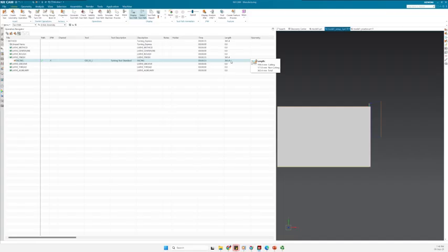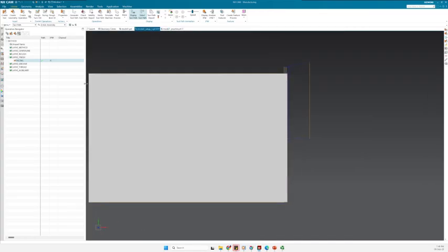So these are all important when you are counting for the time that is finally defining the price, the cost of your manufacturing. With the parameter settings that I did, it estimates that it takes 23 seconds for doing this cut. All right, so this is this operation, and then we go to the next operation, which was the spot drill.